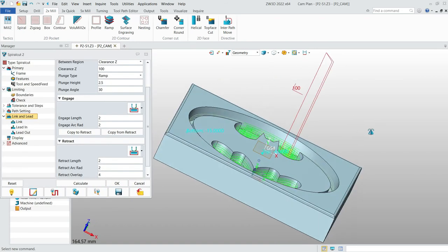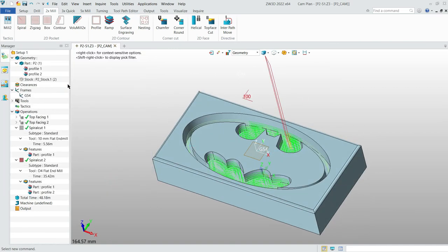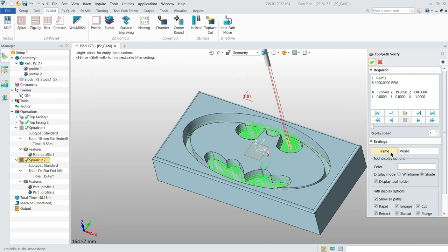Looking good. Nothing so difficult. So let us go through it. You can actually do the detail verify from that previous screen, but we want to do it over here. It's still okay. So G54. Let us play. You can see that the Z is actually -6. So this is the first cut. We can do faster by dragging this. Ultimately it is 16.5. So seems correct. The tool path, so we click OK.